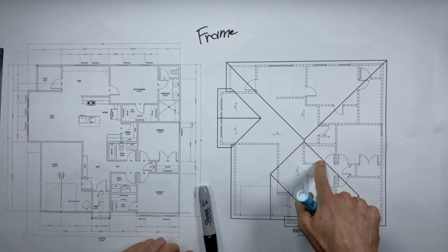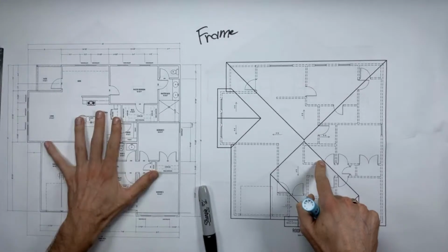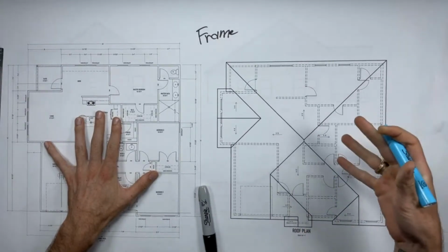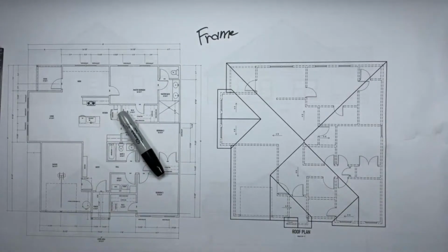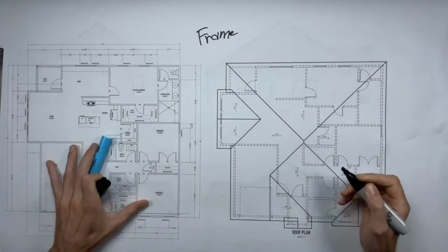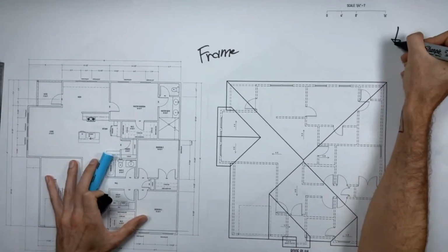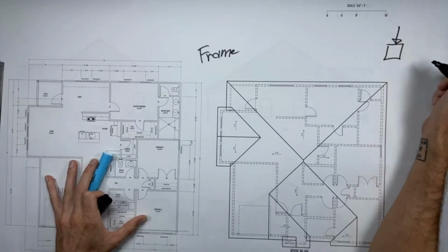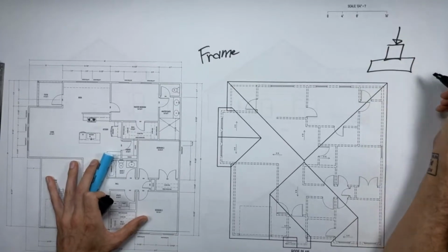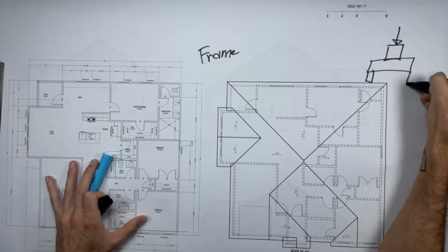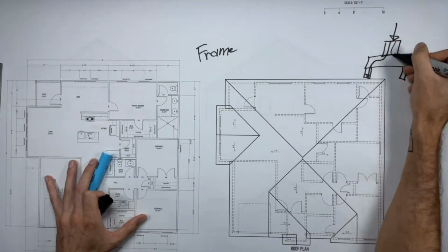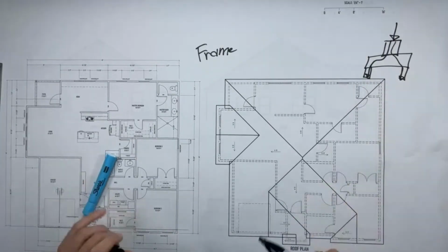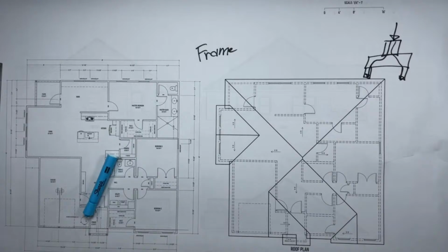This is the roof plan. That's where we're going to put the ceiling plan. So let's start with the roof, because we're going to start from the top and work our way down through the building. Our goal here is to take loads that are up high. They're going to go through various wood members, maybe some beams, maybe some posts. We're going to disperse the load through structural members, and our goal is to get it down into the foundation. That is the point of what we do.